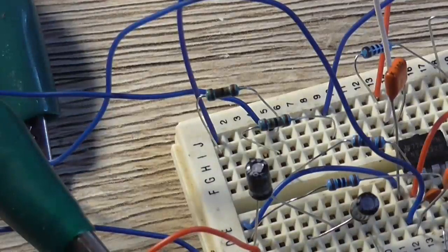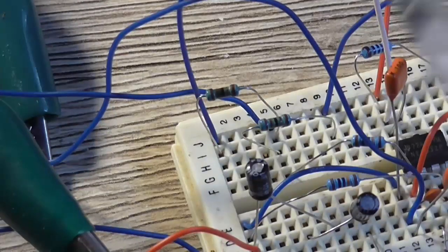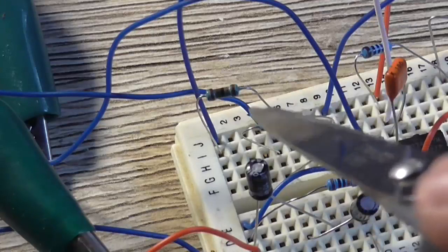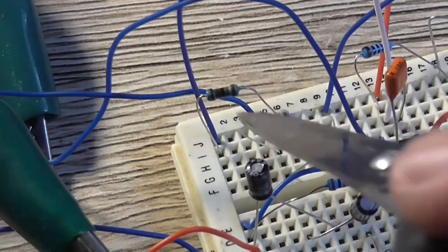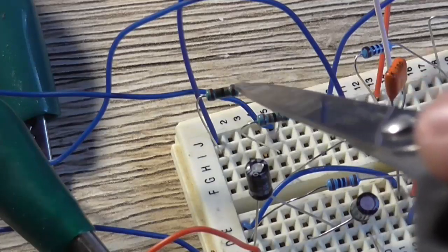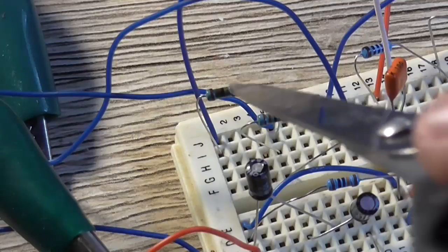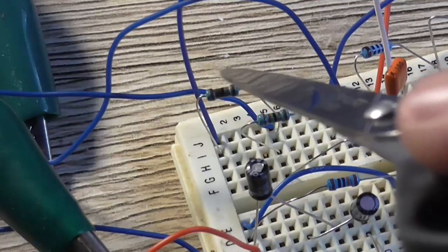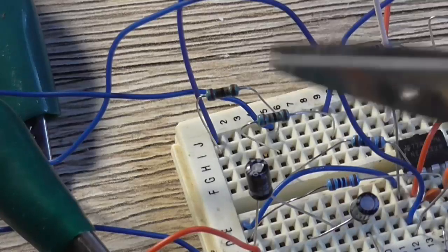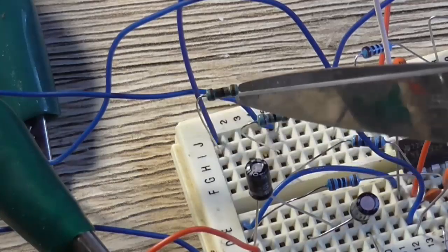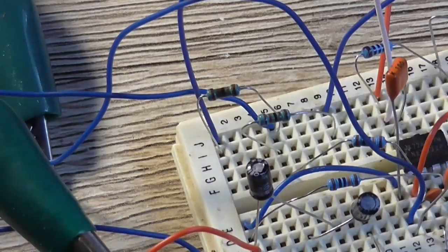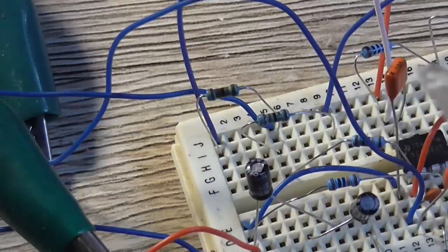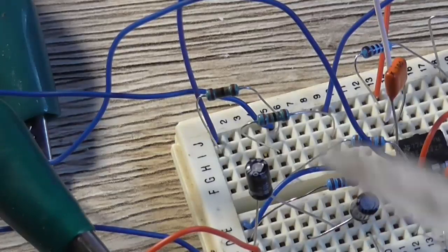Just one other thing to note with this design, I've used 1/2 watt metal film resistors for the 22 ohm resistors. They're very underrated for the job. I would consider quite strongly, because they were getting quite hot when it was driving the speaker, and this one started to discolor, meaning it's starting to burn, at least 1 to 2 watt devices. 5 watt would be excellent there.